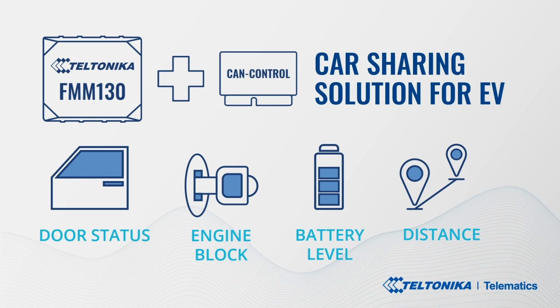And everybody is curious about how to get ignition from electric vehicles. The ignition indication on electric vehicles is connected to a component which switches on when the ignition of the vehicle is on. For example, from the voltage cable of the lamp height adjustment switch, using a clip or strapping the wires. Additionally, I want to say that CAN control supports most popular electric vehicles, and the list is constantly updated to match new models for the most popular cars.